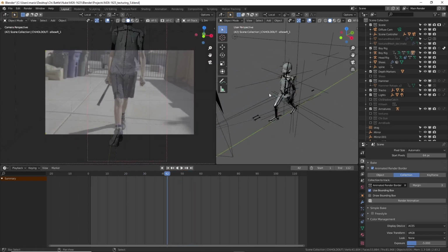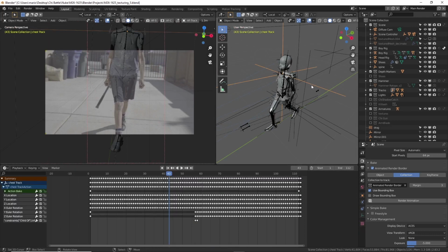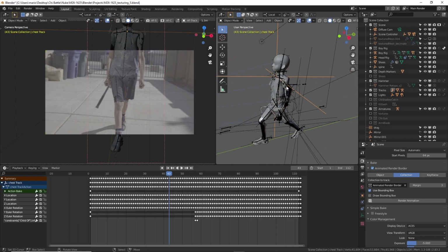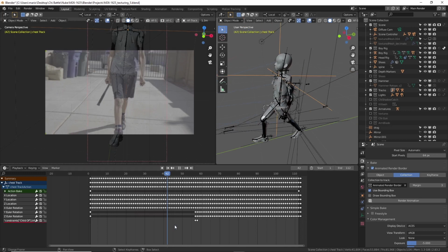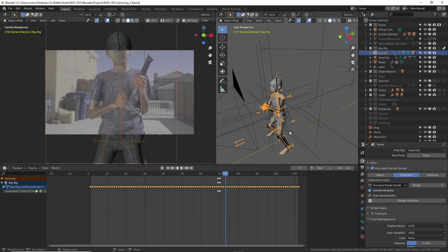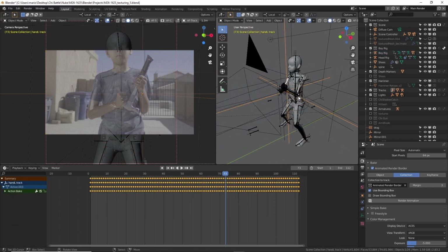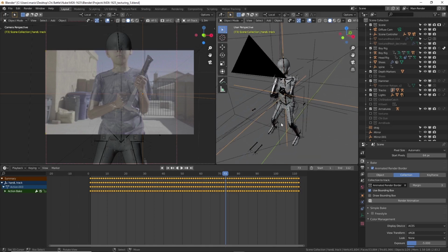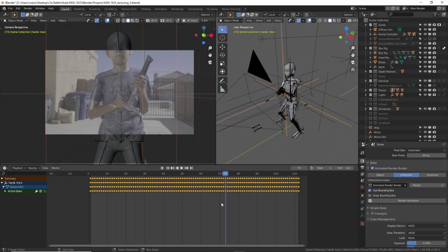All right, so you're probably wondering what all these different things are. It took a lot of constraints and other things to have things move smoothly and well. All of these empties and stuff are just to help better control and add additional animation onto some of these bones, because you can only add one set of animation per bone.